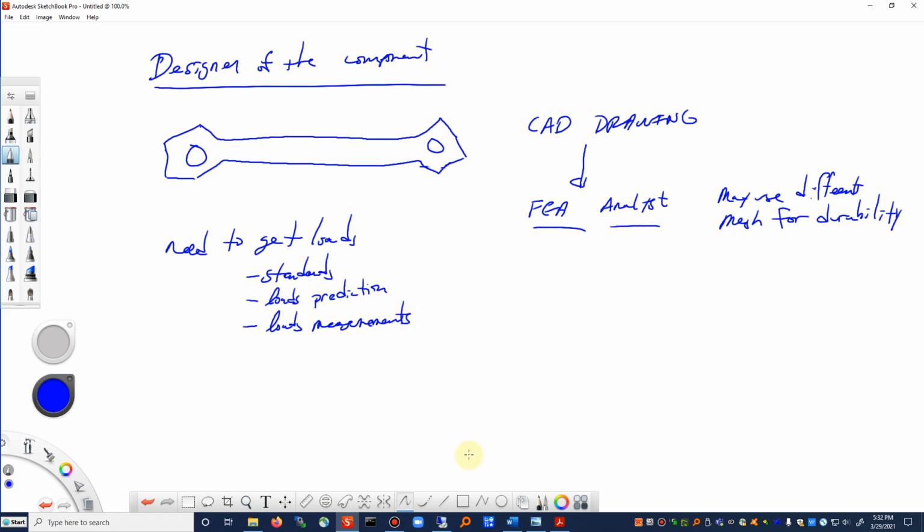So a mule is a cross between a donkey and a horse. Okay, so a mule vehicle is you take an existing vehicle that looks similar to the one that's going to come out, and maybe you modify the suspension and put your new suspension in the old vehicle frame or body, and then you do your measurement. So you can have your loads measurements in that way.